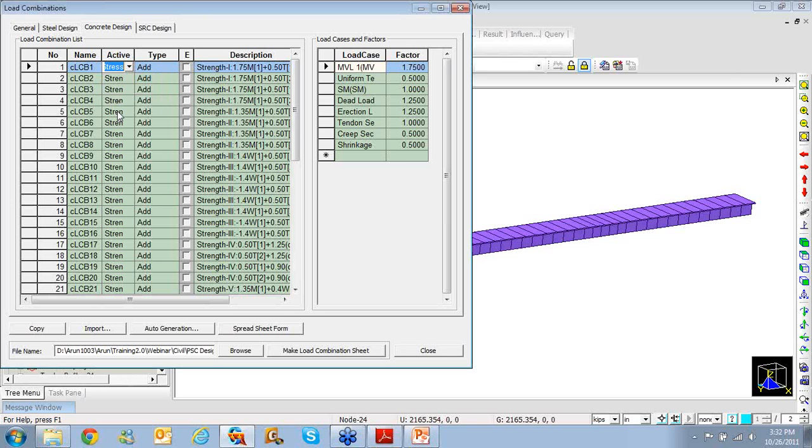So in this manner you can control where you want to use the load combinations. And also when you have several load cases within a load combination, you can choose to have their addition based on simply add or envelope effect. So you can choose between these two effects in Midas Civil.